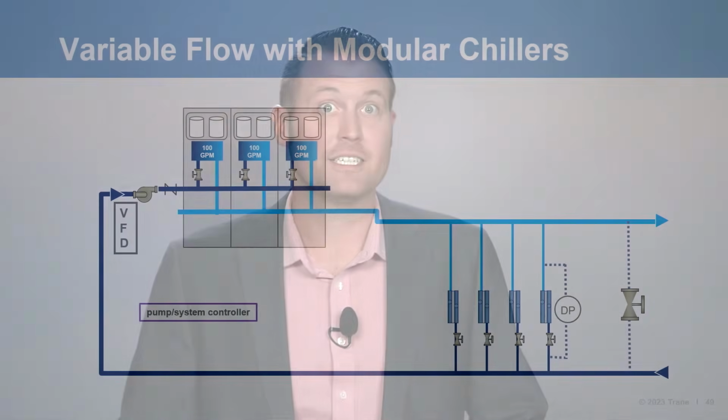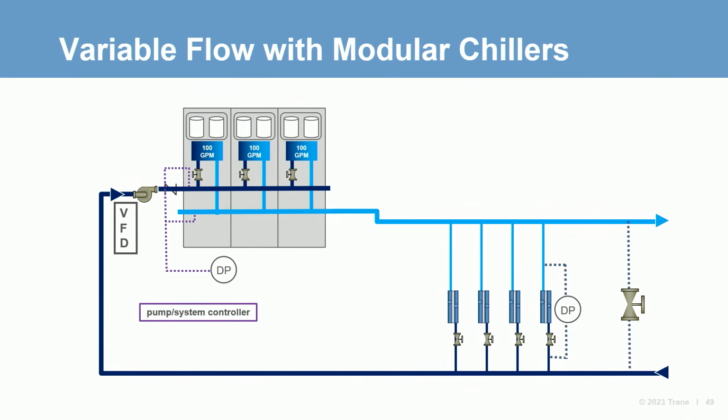In this example, the pumps always keep the chiller satisfied, and the end-of-loop bypass maintains system pressure and ensures minimum flow to the chiller. Another potential control strategy could utilize differential pressure instead of an output from the chiller controller and a flow meter. In this configuration, a chiller differential pressure is maintained by the pump. The pumps are controlled to a constant chiller differential pressure.